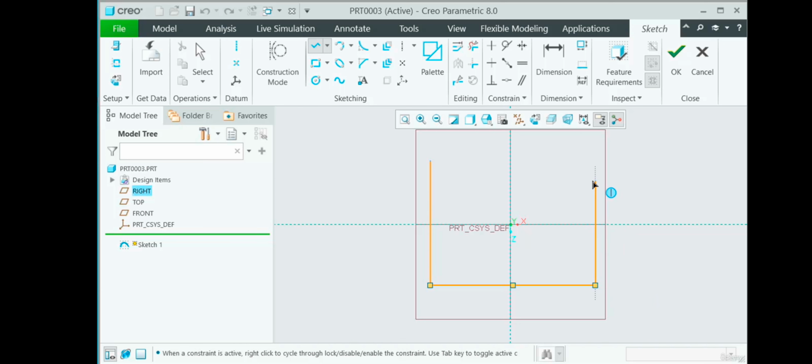When you move up, you can see there are few constraints that are getting generated. If you move, you can see at this point, there is also an equal constraint that is being given. You can see equal constraint. When I click here and again move, if I come here, automatically the coincidence constraint is getting generated. When I click, you can see the rectangle has been formed.